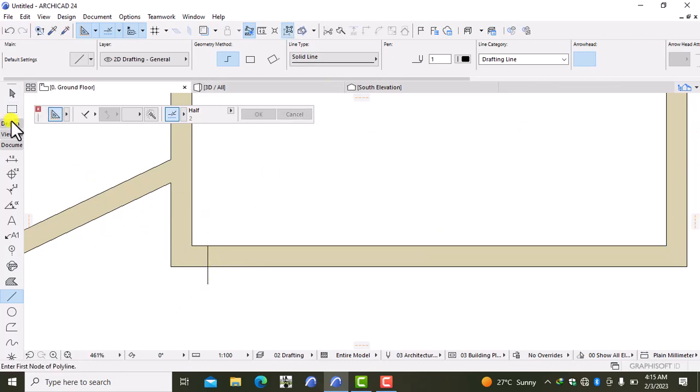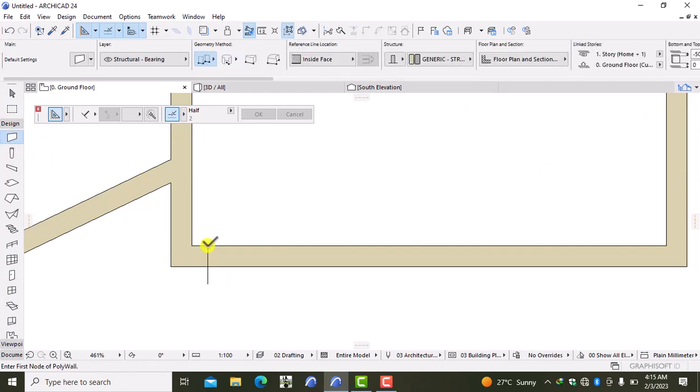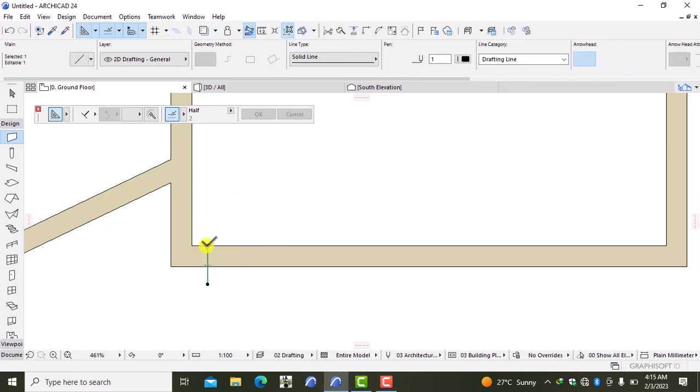So that is my guide tool. I'm going to do a wall over here. In fact, let me just drag this line to a known distance, so I'll drag it to a distance of 300, and internally I can drag it to a distance of 200, also maybe let's say 500. Yeah, something like that.